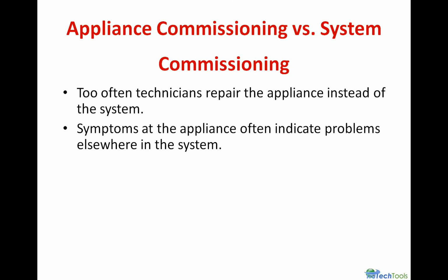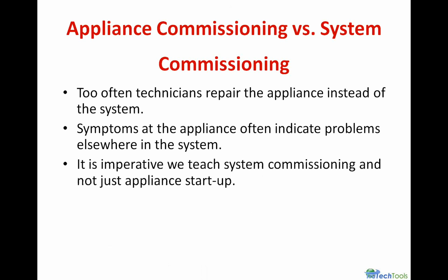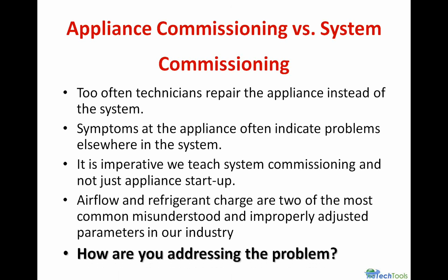It could be an airflow problem. We've got to look at the system as a whole. It's imperative that we teach system commissioning and not just appliance startup. All these systems, because they're field installed, require a field commissioning procedure. Airflow and refrigerant charge are two of the most misunderstood and improperly adjusted parameters in our industry, period. And the question is, how are you addressing the problem?